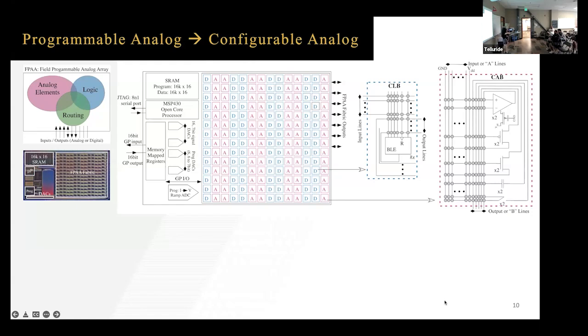It's the interconnect, all the floating gates. Yes, everything is floating gates in this chip. So all the way through the digital and analog stuff, which is actually nice on the digital part because it really gets the leakage way down compared to a typical FPGA. So when I want to turn something off, it's way off. But you would still need a programming transistor to select the floating gates to program.